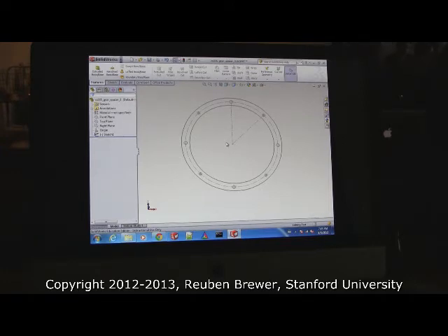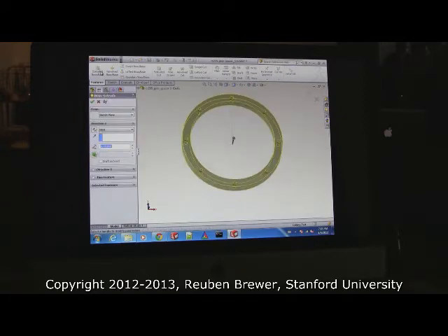So you can start an extrude either on a plane from blank and then make a sketch and extrude, or you can start from a sketch and just extrude that. So click the sketch and then go SolidWorks and then click the extrude boss base thing. Boom, we're back in business.